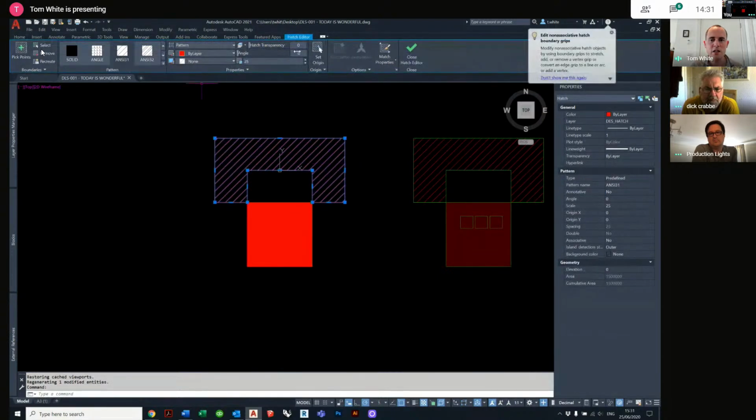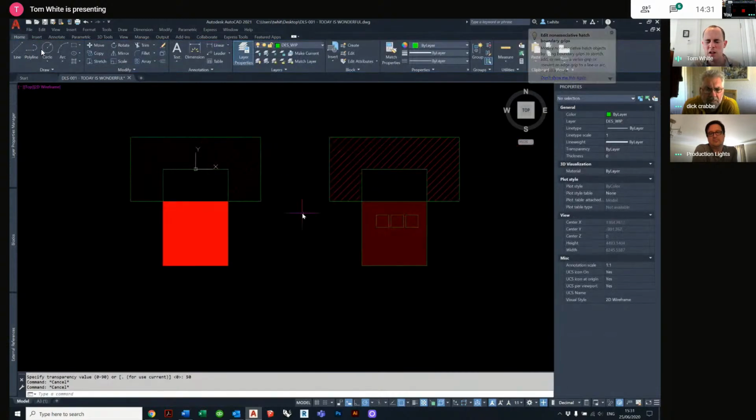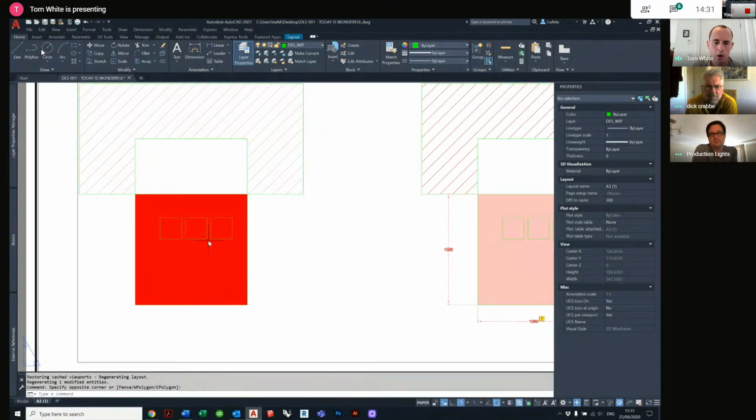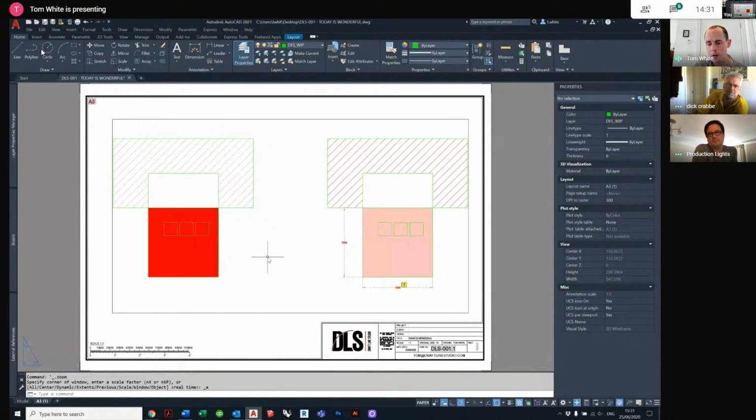If I desire, I could change this transparency to 50%, so it dies down a bit. I could also do another thing. I could use a command called hatch to back. The left-hand side and the right-hand side are telling us identical things, but because the color 10, I believe, I chose for this hatch is so prominent, it's a little bit hard to see what those chairs are in between in this area. So a transparency is a great way of knocking back the color slightly in a quick manner that makes what you're trying to tell an easier story to understand.